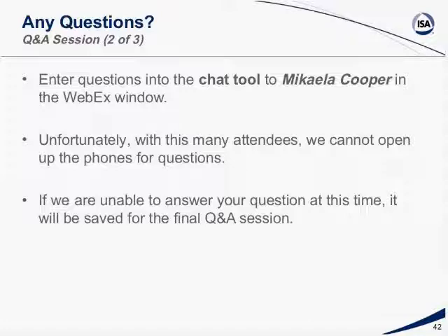For example, I went to a terminal facility last year to do a rationalization. They had about 500 tanks sitting out there. As opposed to rationalizing each of the 500 tanks, we took a look at the scenarios for tanks. We had tanks at atmospheric conditions, tanks that were heated, tanks that were cooled. We had tanks with hazardous materials and tanks without. So what we ended up doing is rationalizing the scenarios, and we essentially did 500 tanks in 2 days.